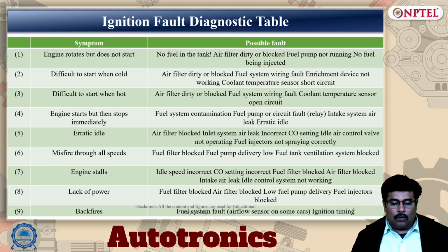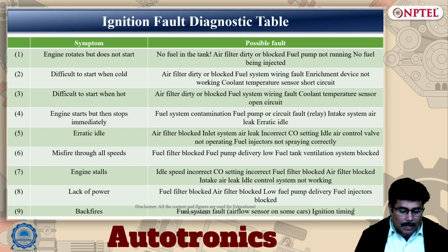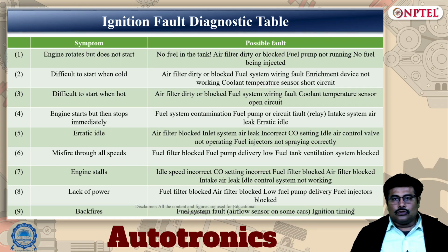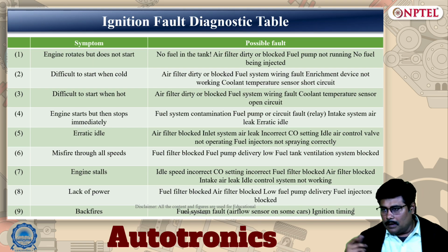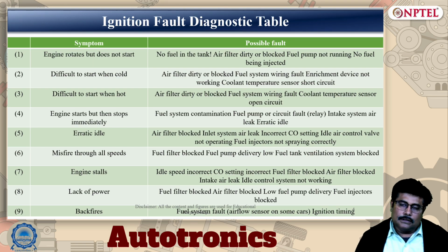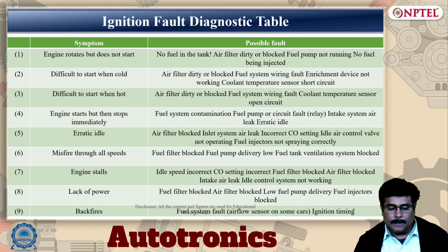Now, if we look at the overall symptoms as well as the possible faults from an ignition fault diagnostic table perspective, the first symptom we normally see is that the engine rotates but doesn't start. The possible faults may be no fuel in the tank, a dirty or blocked air filter, the fuel pump not running, and no fuel being injected.